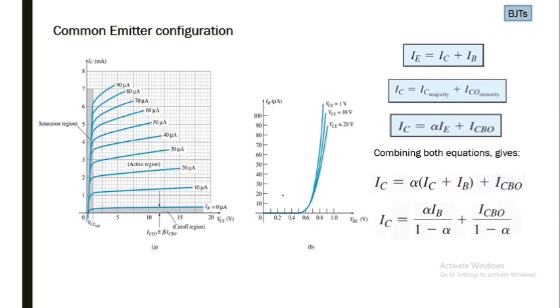And if we remember the forward bias condition of diode or a PN junction, the curves are similar to that one, that is a forward bias diode. And if you consider the material as silicon material, then the knee voltage is around 0.7 volt.